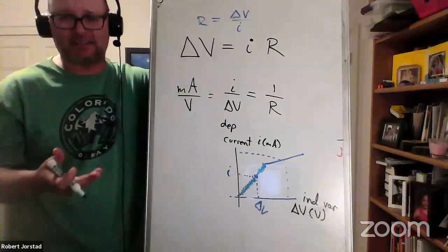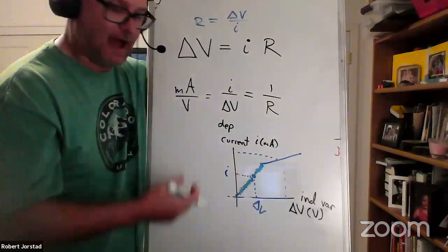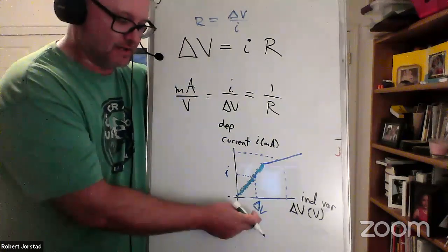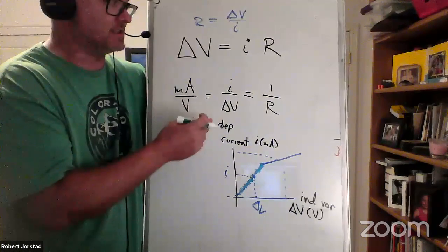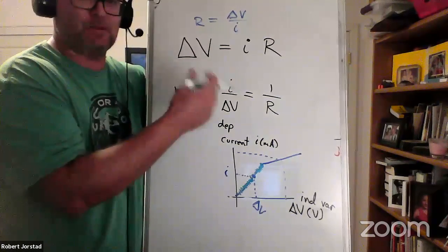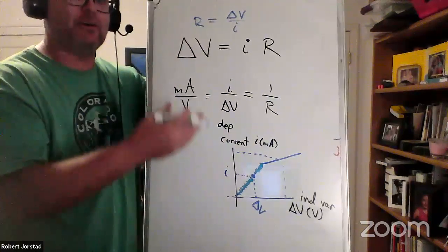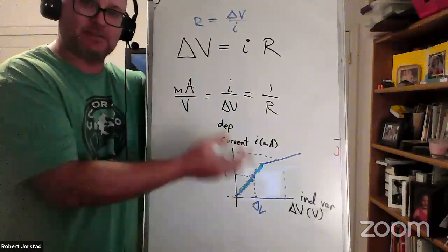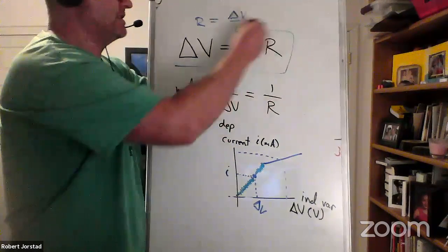So in practice, what is going to happen tomorrow? I know it's time to go. This is the idea: I use a power supply and record the voltage across the power supply and the voltage across a resistor. If you know that resistance, you could figure out the current. That's going to help you figure out the resistance of this other resistor. Then we're going to see how that resistance changes versus length. So we're going to be using both this voltage idea and this equation.